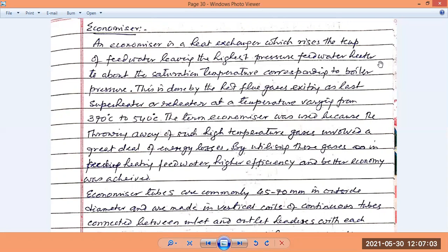Then a portion goes to the de-superheater and the secondary superheater, and then it goes back again to the air heater, where it transfers its remaining heat to the air as well as to the oxygen itself. But for a few reasons it still has a temperature of around 460 degrees centigrade, which is sufficiently high that you have to use it somewhere. So there are certain problems, and you cannot drop the temperature any further at this stage.